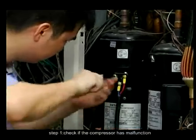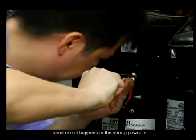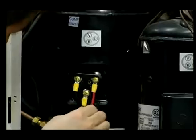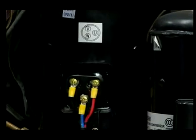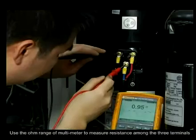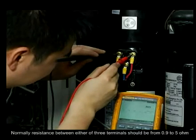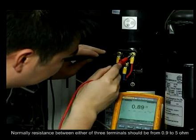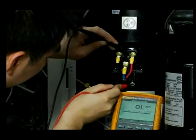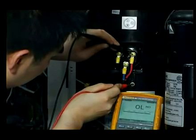Step 1. Check if the compressor has a malfunction, a short circuit, or if the terminals of strong power are not tight. Use the ohm range of the multimeter to measure the resistance among the 3 terminals. Normally, the resistance between any two of the 3 terminals should be 0.9 to 5 ohm, and the resistance between terminals and ground should be infinite. If the resistance is abnormal, please change the compressor.